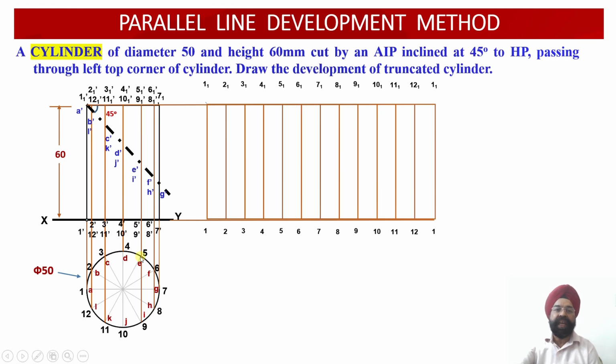The instruments I have are the divider, the scale, and the compass. So my compass, scale or divider will be measuring the linear distance between point 1 and 2. They will not be measuring this arc distance. So this is an approximation method: whenever in manual drawing we mark all these 12 points, ideally the distance between point 1 and point 2, and similarly between all the subsequent points, should be equal to 2 pi r divided by 12, so that the 12 sectors are available.